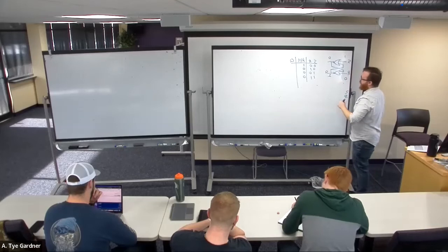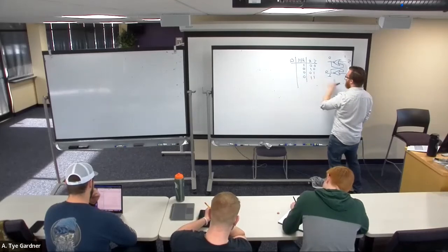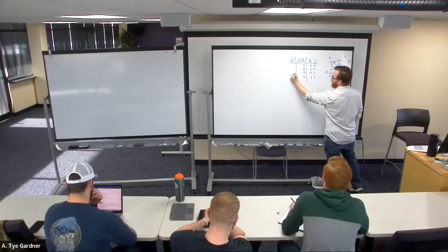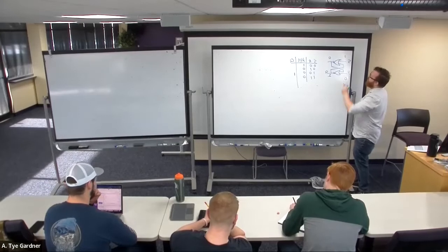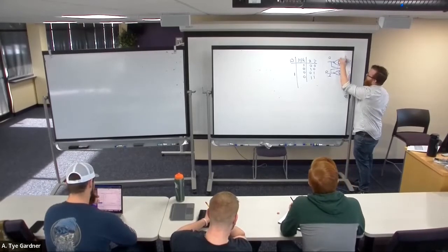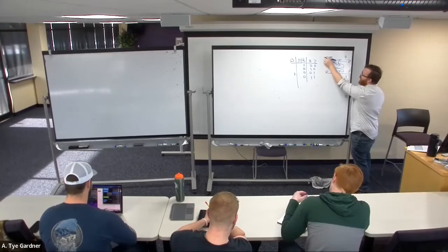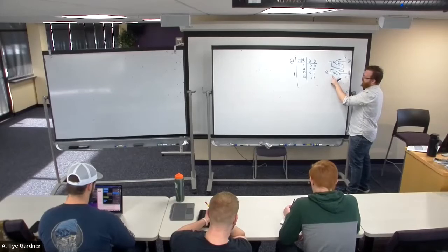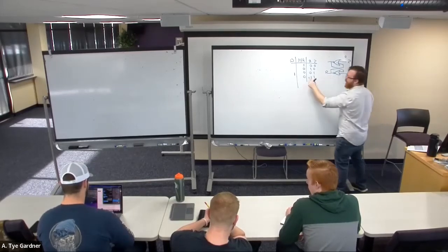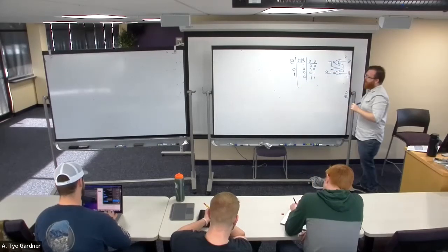So in the case of Q, if S is 1 and R is 0, I get Q is 1. All right, what happens if I flip that? If I have a 0 and a 1 here. Well, in that case, we have a 1, which means any 1 means Q is 0. So R is 1, Q is 0. There we go.